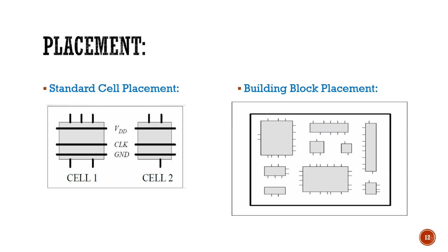Even I can place my power supply at the bottom, and I can take an adapter and connect it at the bottom of the design. This is what is done in building block placement. So while you are placing a block, either standard designs can be followed, or you can place the block on your own. That is what placement represents. After placing the blocks, before making the interconnections, the major step that is involved is clock tree synthesis.